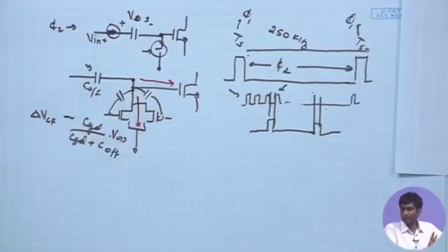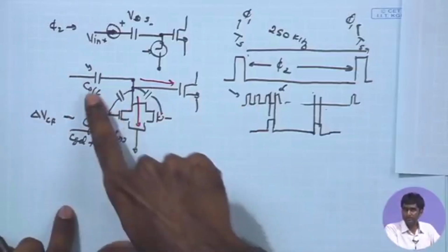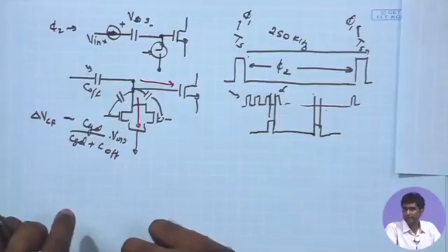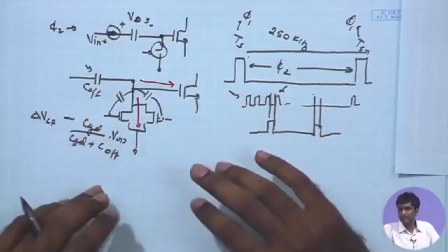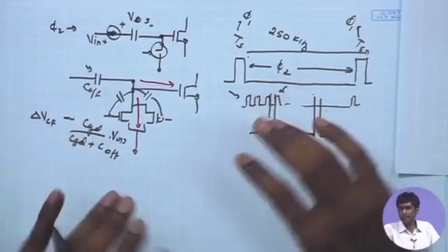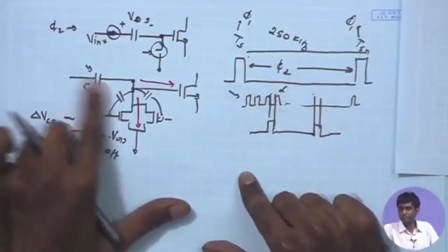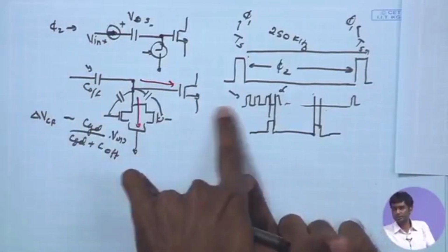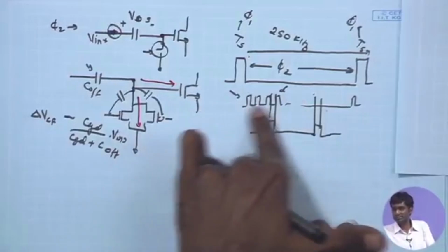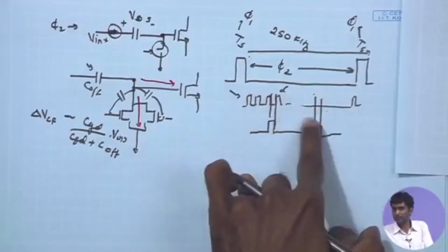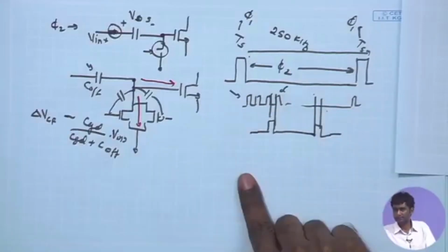Therefore, if I look at the overall design, whatever we have as of now, this is not contributing a huge amount of area as compared to the bigger capacitor that we have. But if it is becoming very area critical and saving every micrometer square is important, then definitely we can go for options where you can minimize the areas because of these capacitors. And in those cases, the only thing you need to do is have a little bit more sophisticated digital control, which is going to help you in implementing the appropriate timing pulses.